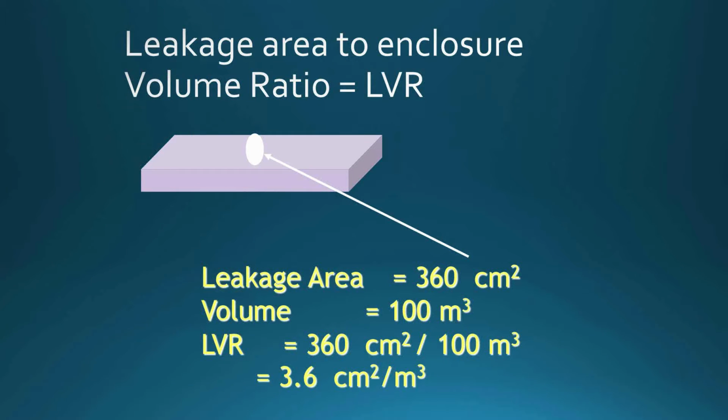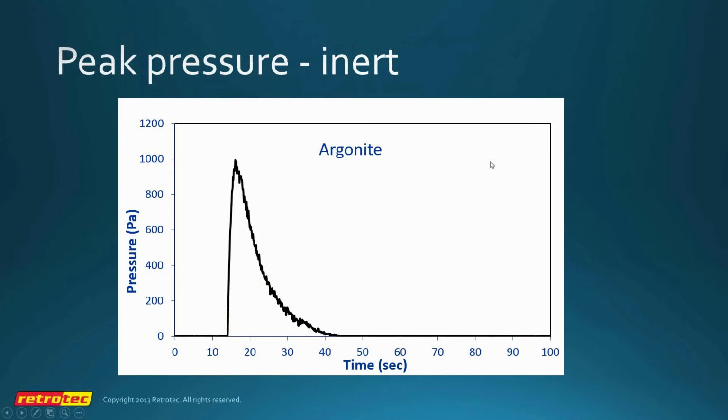The primary determinant of peak pressure is the leak to volume ratio, which is measured by the door fan. What was unique about our research project was that it related the door fan test over a wide range of enclosure leakages to the peak pressure, and this was the first time this was ever done before. The data from the past all showed a whole bunch of data in one clump in the middle, and we were unable to determine the shape of the curve.